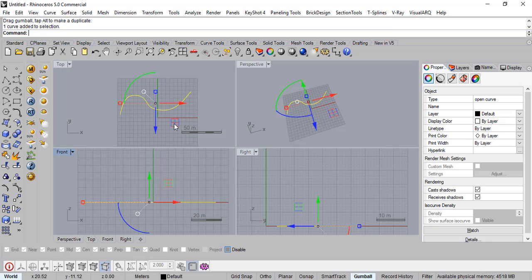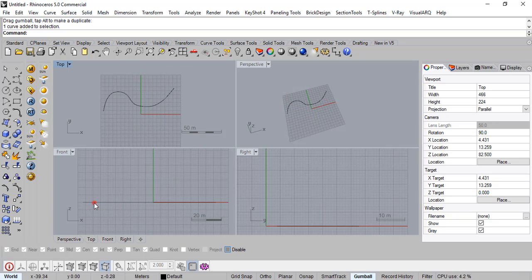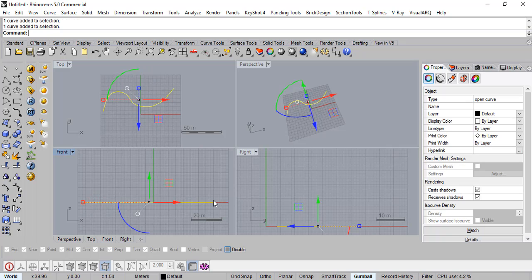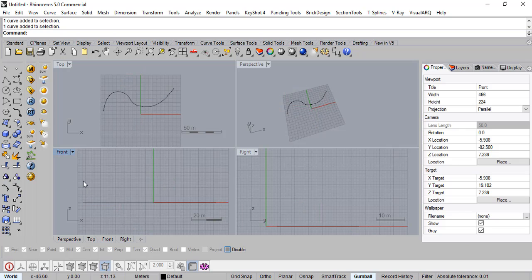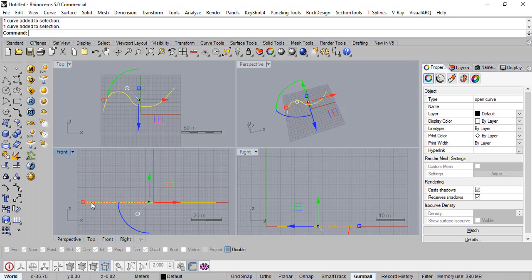How this technique works is you should know the limits. So these are the limits of the first curve, right? The second curve that you're going to draw that needs to resemble the shape in the elevation has to be within these constraints, for which I'll use one of the OSNAP buttons.